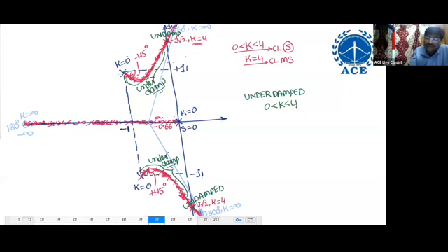It is left. Then complex poles are at this point, so that it is underdamped. Because there is one single pole on the real axis, complex poles are there. We'll consider only the complex pole response. That's why K greater than 0, less than 4, underdamped. K equal to 4, the system is an undamped system. So this completes the problem.